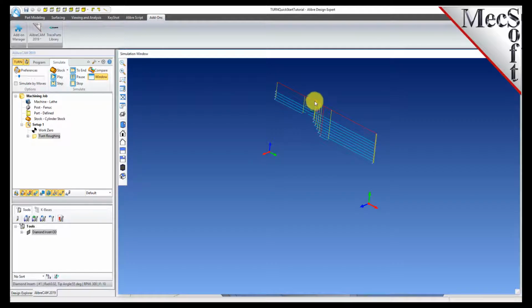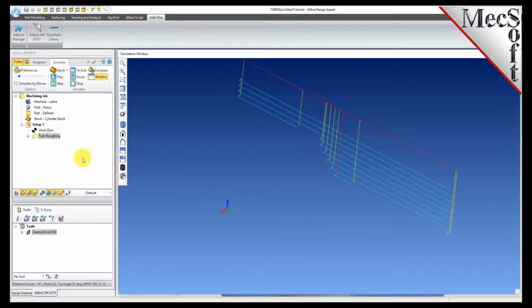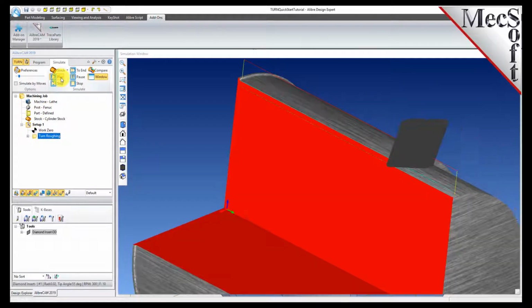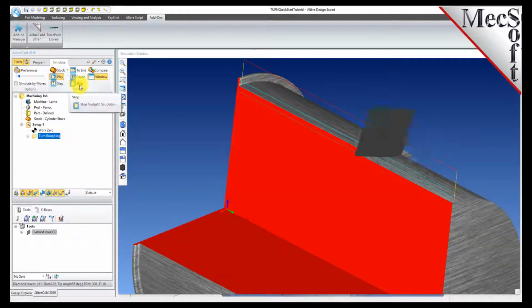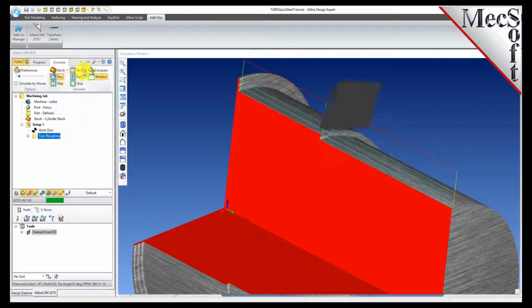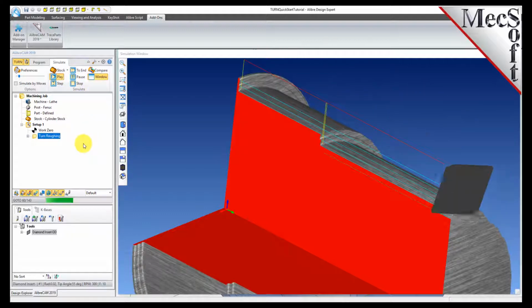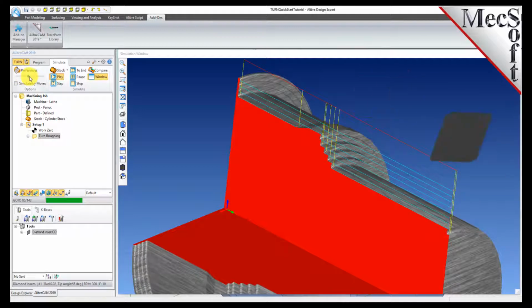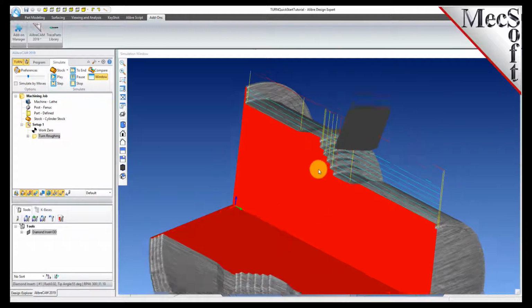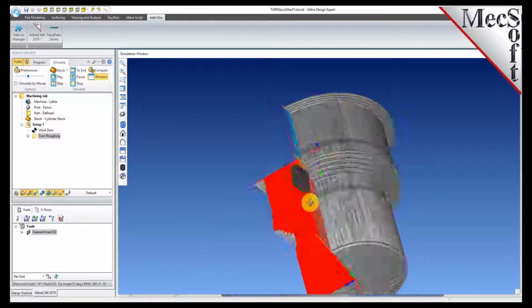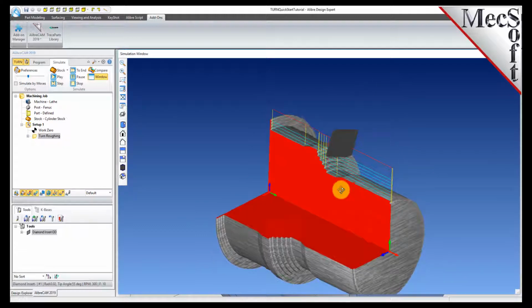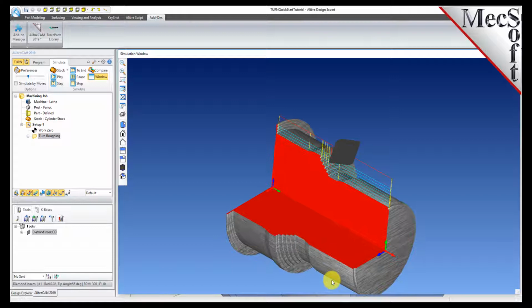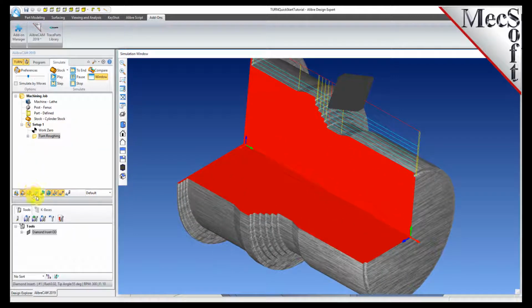Now select the Turn Roughing operation and pick Play. Additional simulation controls are available on the menu, such as stop, pause, etc. Once the simulation is complete, the state of the stock model is displayed on the graphic screen. To view the cut model with textures applied, select the Material Texture Visibility icon located at the base of the machining browser.